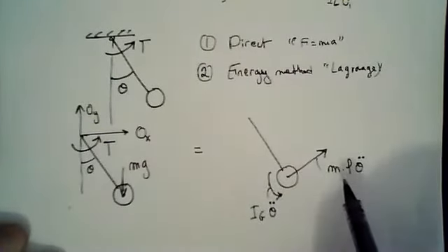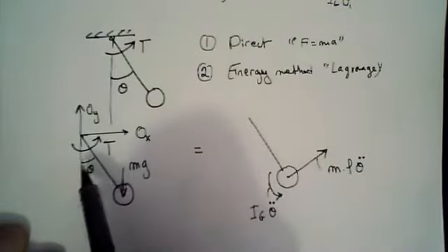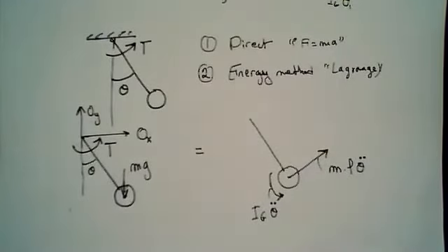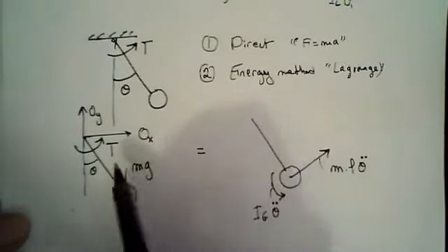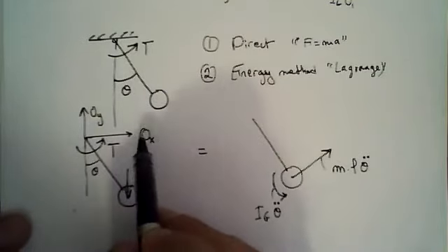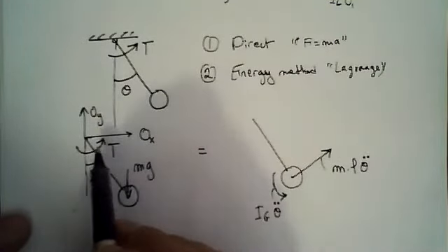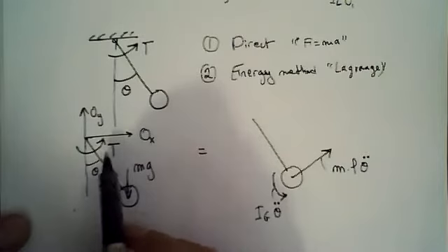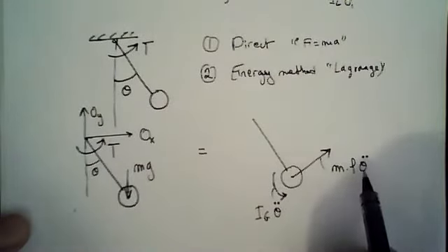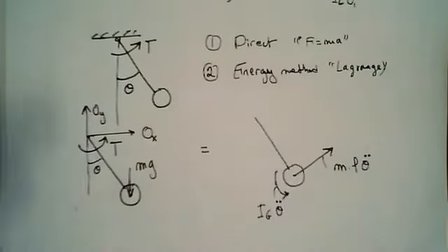Same thing for the acceleration. We're going to assume that theta is increasing. What would be the acceleration of this point? Okay, now we need to continue and find the relationship here. In forward dynamics, I'm not really interested in OX and OY. I'm only interested in finding a relationship between the torque, where the motor is located, and the angular acceleration. So I'm trying to relate how that thing will accelerate if I apply torque.